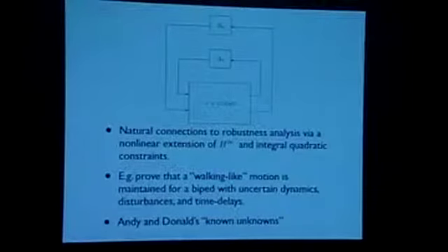I will mention for future work, there are very deep and very natural connections between the Lyapunov analysis that we're doing here and robustness analysis via nonlinear extensions of H-infinity integral quadratic constraints. So instead of searching for Lyapunov functions, we're searching for storage functions that verify interconnections of various system components are going to be stable. That could be time delays, that could be energy-bounded uncertain elements, infinite dimensional elements, and so on.